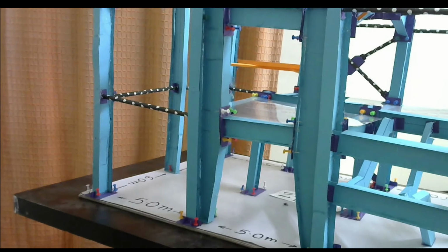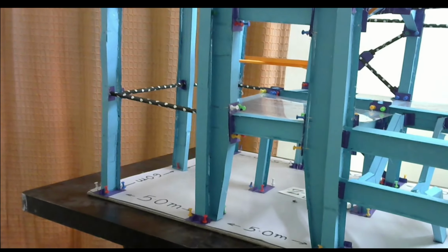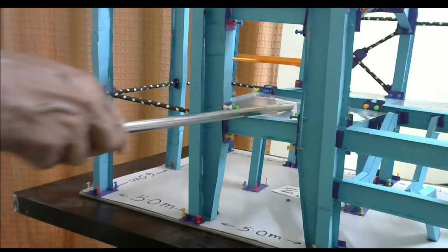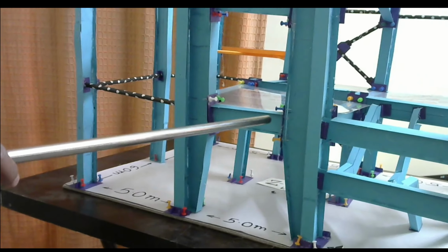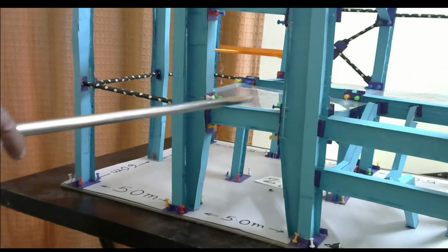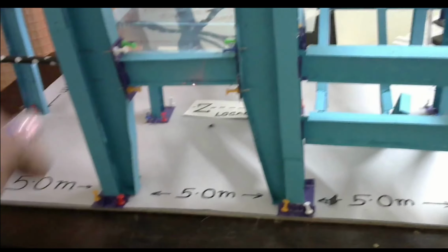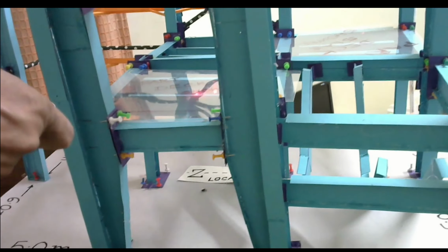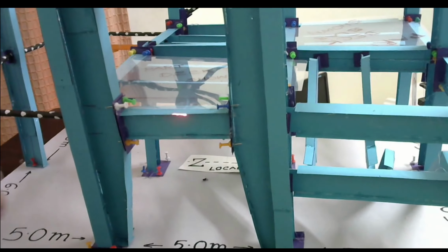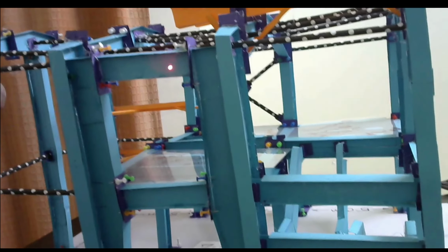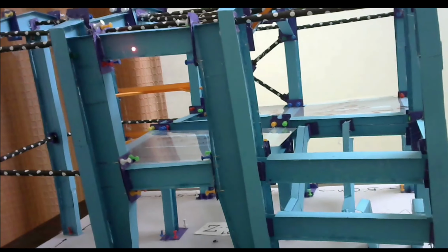For any practical purposes, if we want to economize, we can provide a beam at the center connecting to this joist, and then the effective length LX, LY will be 2.5 meter if we provide a beam along this part to this joist, connecting a simple beam, so that will provide restraint. In that case, 5 meter divided by 2, LX, LY will be 2.5 meter, but LZ will remain 5 meter. Now for this case we cannot provide any top beam, so for this beam LX, LY, LZ all will be 5 meter.